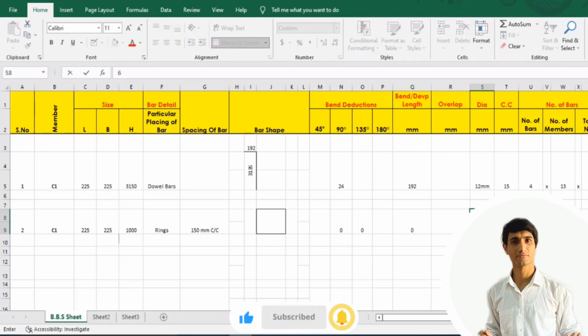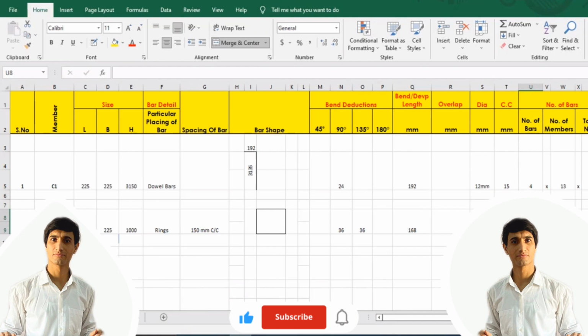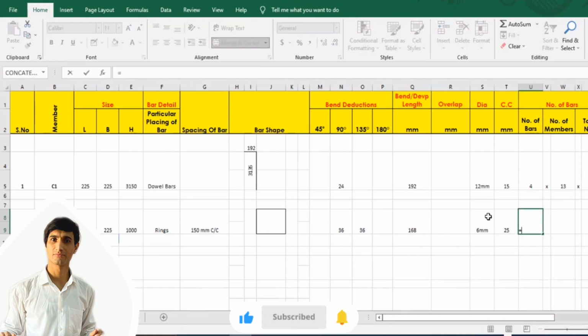What is the dia of bar? 6 mm we are using here for the rings. Concrete cover here in the columns is 25 mm, and the number of bars will be equal to the span. The span is 1000, top and bottom I am talking about, 500 at the bottom, 500 at the top. Span divided by spacing over here, plus 1.